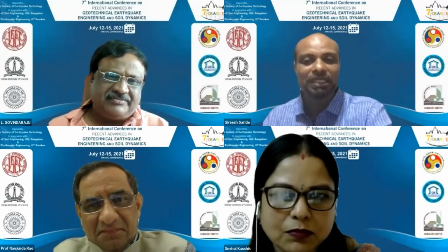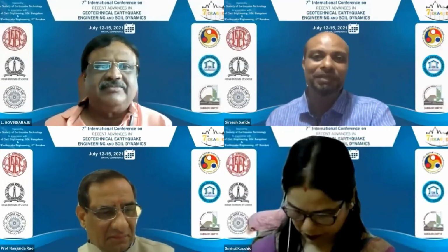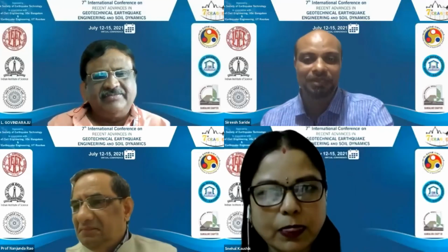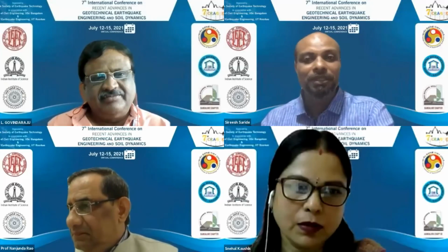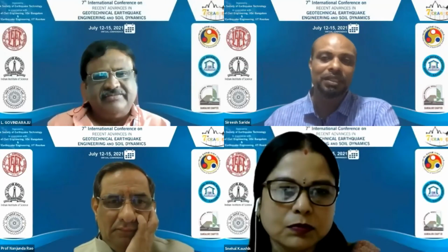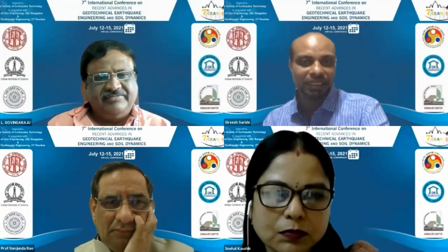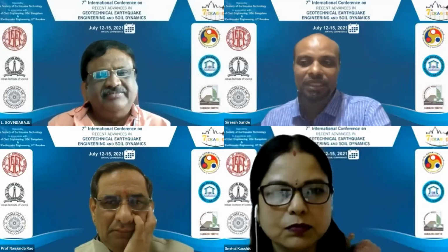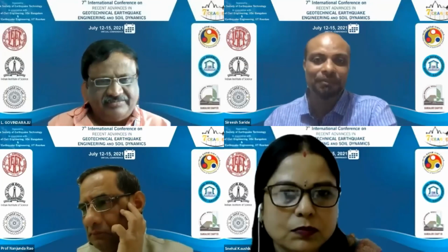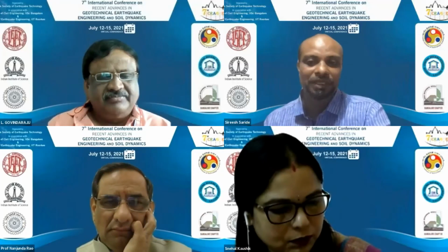And this sodium silicate and sodium hydroxide combination is also exothermic, so we just cannot dump the material there. I showed some pictures, but I could not get into the details because of time. We need to prepare the mixture a day before, at least this combination of sodium silicate and sodium hydroxide, but should not mix it with the fly ash and other aggregates. That goes the next day. And we need to do this in the late evening or late night, where temperatures are low, because it will produce a lot of heat from exothermic reactions.